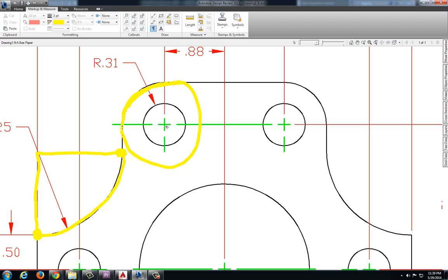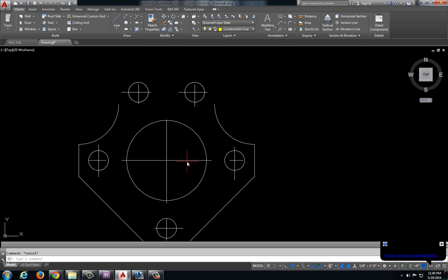We know that our center point is right here, and we know where to start it, but we don't know how far out to make it. Well, if we look a little bit closer, if we take our right quadrant point and draw a line straight up, then we can create a circle with a radius, start our center point in the center that we've already identified, and just bring that straight out until we hit our vertical line. So let's see what that's going to look like.